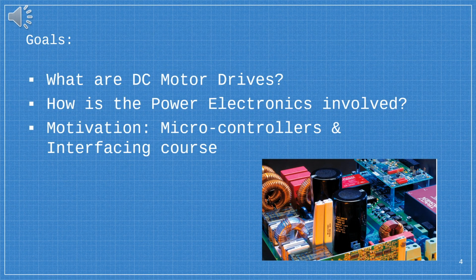Let us start off by discussing what motor drives are. Well, in essence, motor drives allow us the ability to control certain variables of a motor, such as their speed and their torque, while more importantly, also allowing us to isolate low power control circuitry from the usually high power consuming motors, which could otherwise damage the control circuitry.